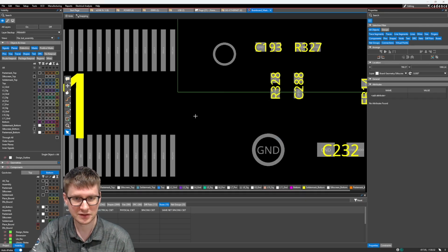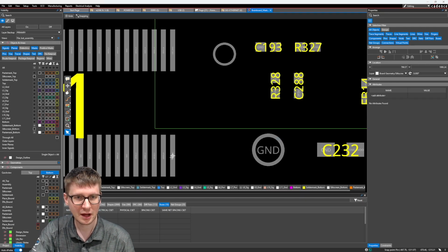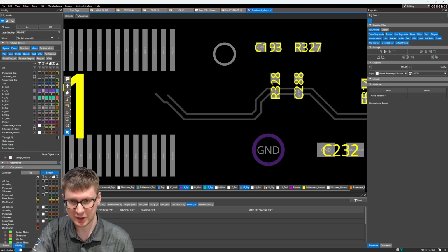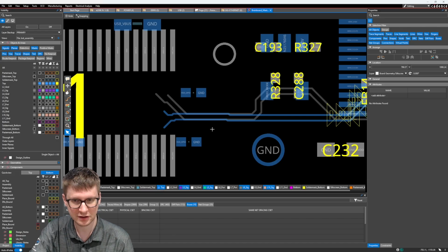And then just click paste. Now again, I was snapping on this first pin here of this component, so we'll go ahead and click right there. And now if we go ahead and turn on our layers, that pasted information should exist on, there it is, the top layer and what looks like the layer 8.